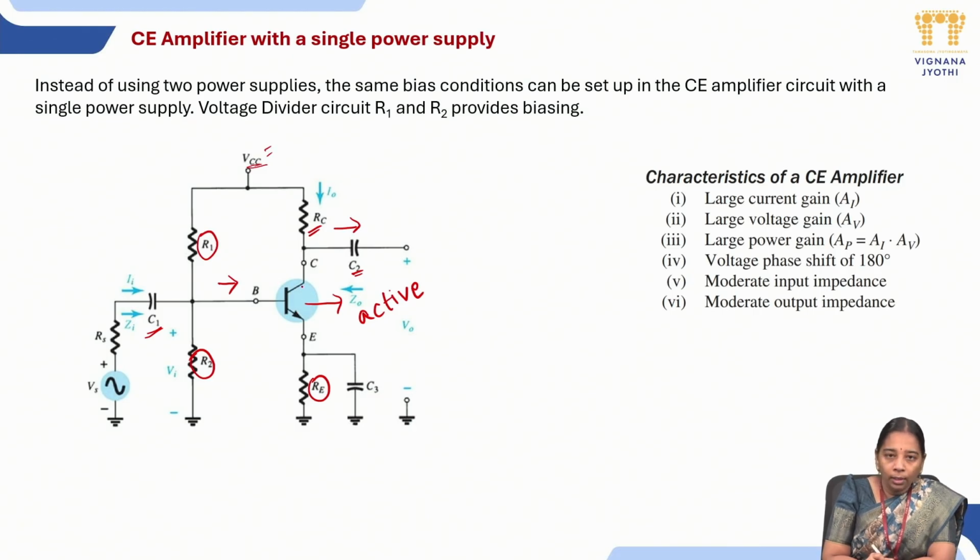The transistor acts as an amplifier and doesn't care whether it is an AC or a DC signal. It amplifies both, but we need only the AC signal to be amplified, so we use coupling capacitors, because a coupling capacitor blocks DC and allows only AC signals to the base.